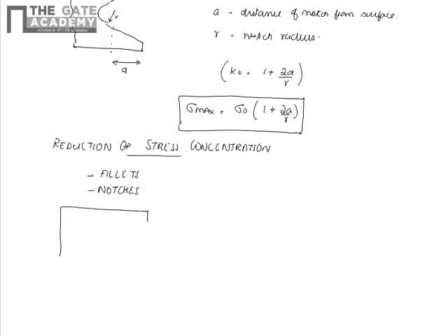Now if we take a specimen like this rectangular body with a circular hole, we know that stress concentration is happening because the stress contours get deviated like this. So these stress contours are deviating and causing concentration of stress in this location. The stress contours get deviated when very near to the circular hole. So how can we reduce this stress concentration factor? By providing additional holes.